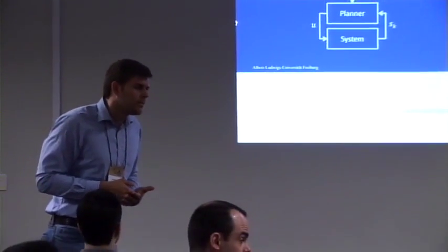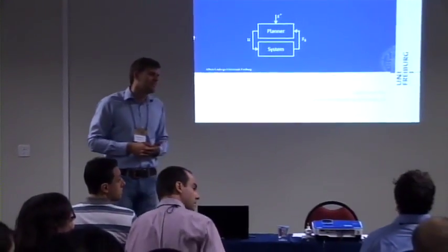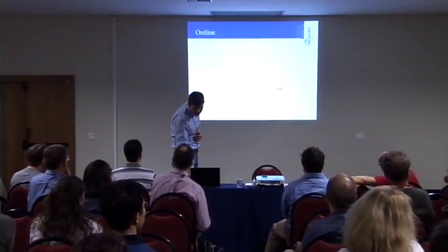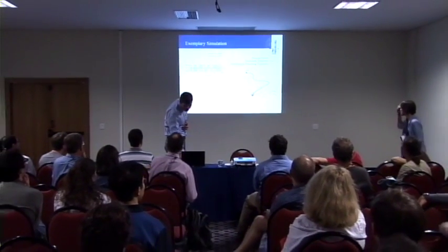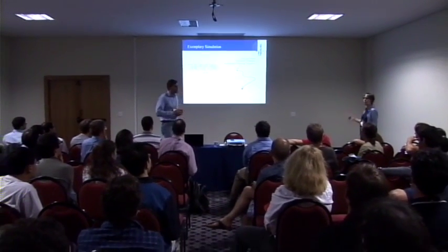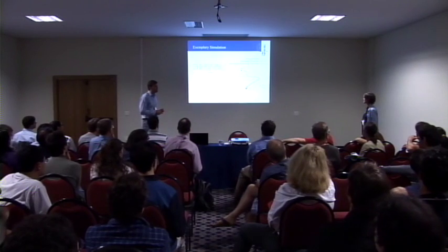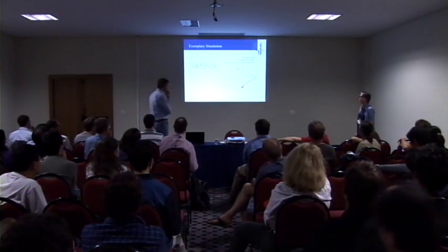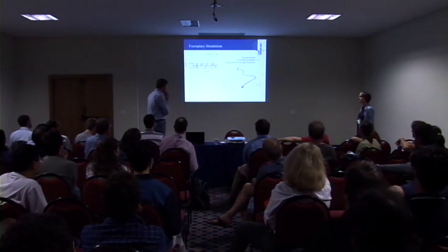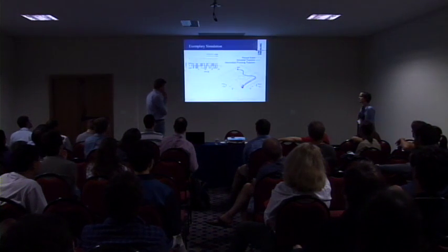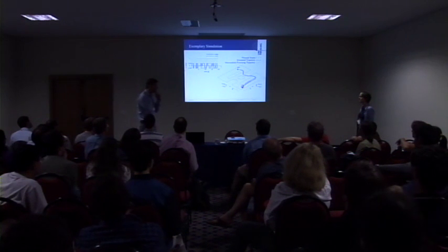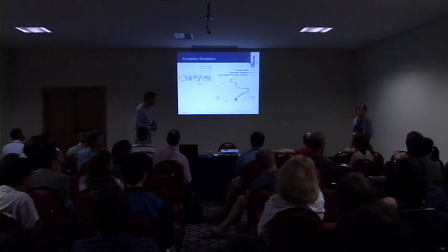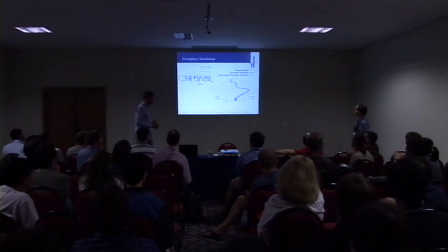Yes, Jonas, thanks for your talk. I had a question on slide 24, 23. You were displaying this trajectory that eventually you want to execute. This one here? Yeah, exactly. And it seems to me there is some trajectory smoothing going on over there. So I was wondering how you can still guarantee that you're not falling into your hole after you've smoothed your trajectory. Where do I have the trajectory smoothing, actually? Well, it seems that your trajectory is not point to point, right? It's like a second order interpolation going on.